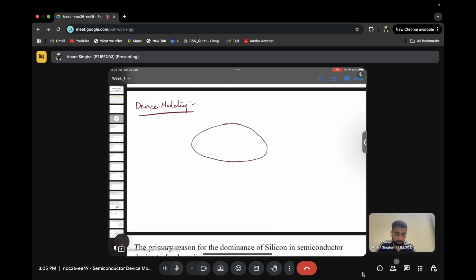So, we have silicon wafers having a certain diameter. Let's say 2-inch wafers, and so on, up to 12-inch wafers. And we fabricate different devices on these wafers using certain processes that are not included in this course, but that is what we call the fabrication of a silicon device. Now, this is just fabricating. What we can do is a lot of device simulations in terms of TCAD, where we design a device even before fabricating it. And why do we do it? Because we want to save a lot of resources.